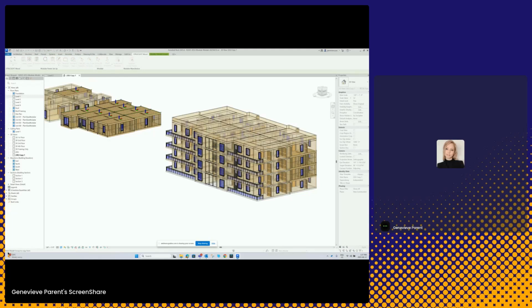And right down here, it is saying select model group to copy from. I want to copy it from this one. I do want to continue my numbering, and my source panel is the parent panel as well. I'm just going to hit OK. So rather than click on one and push the information to all the child groups, we're doing the reverse, where we're saying, okay, I want you to take this model group and go and steal from the group that I am selecting.